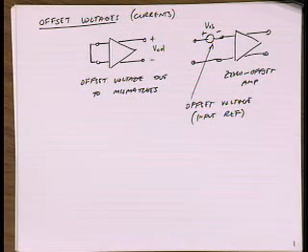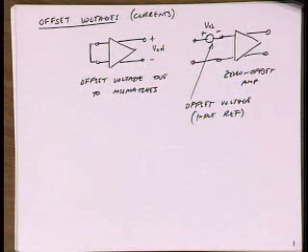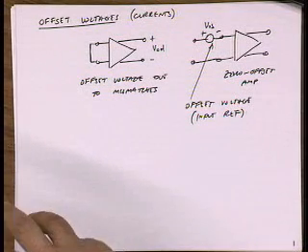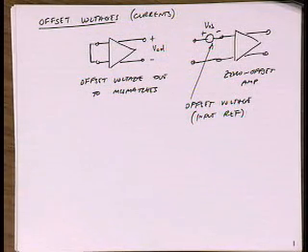In terms of, let's say I'm trying to build a system that's just trying to detect either a positive voltage or a negative voltage. It's very common. Let's say I'm building a magnetic drive, and I want to read bits off of my drive. Based on the directional polarization of the bits, I'll either read a positive voltage or a negative voltage. It's actually a very small voltage. Let's say I build a magnetic coupler and I pick up 1 millivolt signal levels. If it's plus 1 millivolt, that means I recorded a 1. If it's minus 1 millivolt, it means I recorded a 0.